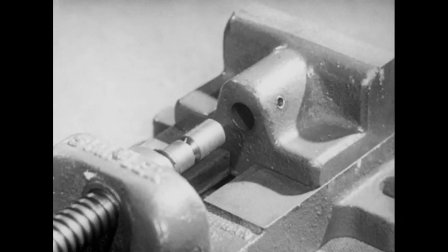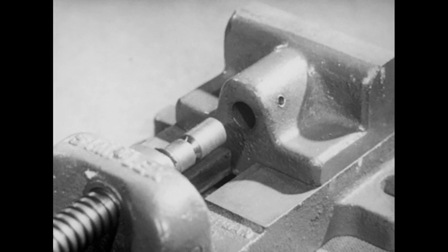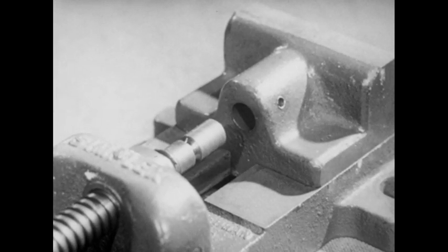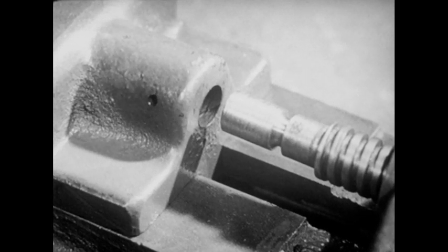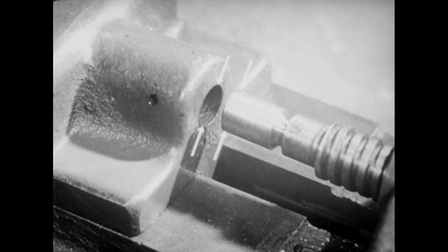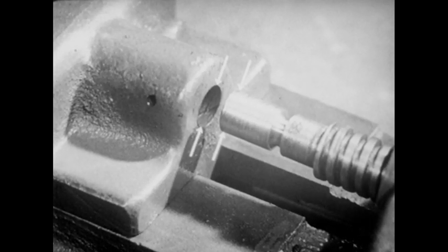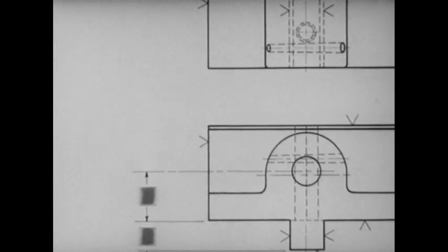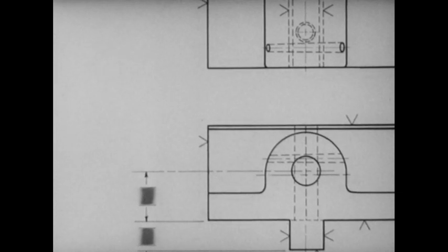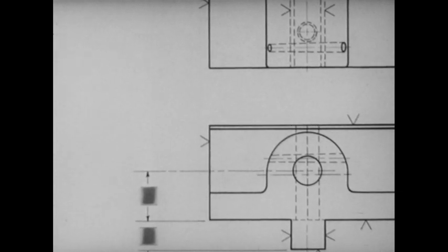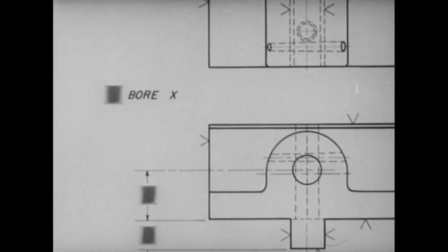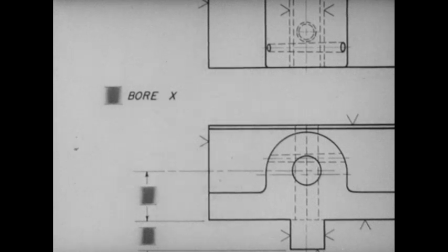The diameter of the hole in the movable jaw must be correlated with the diameter of the cylinder on the end of the shaft. Give the diameter of the shaft cylinder and give the diameter of the hole in the movable jaw. On the drawing, use the diameter instead of the radius, because it is difficult to measure the radius of the hole on the movable jaw. Specify this diameter as a bore note, because boring is necessary to produce a flat bottom in the hole.